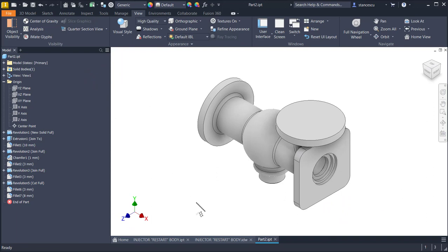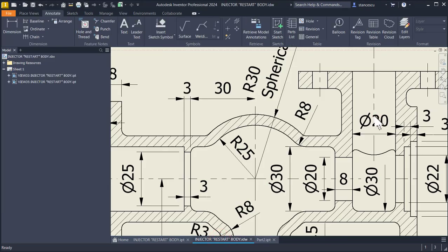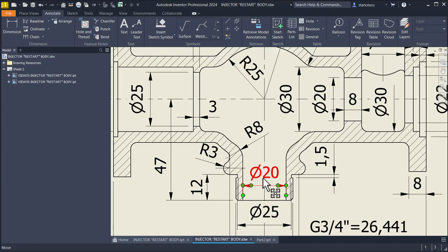and all we have now to apply are holes. Now we apply 2 holes, this one 20 and this one 20, from the face to the mid plane, this mid plane. We don't forget that there is a radius of 8 here.